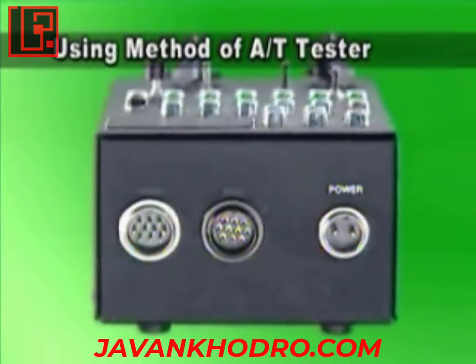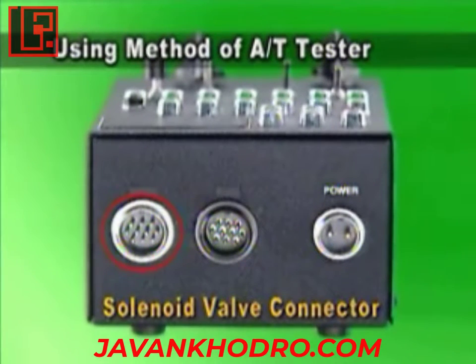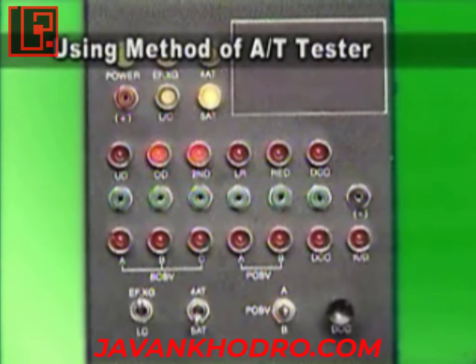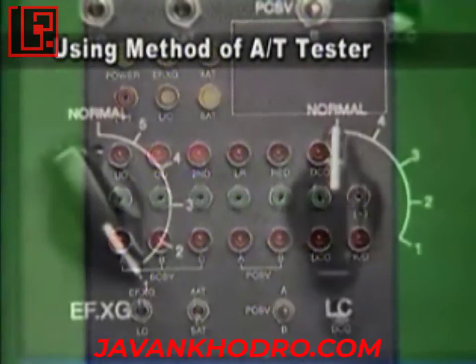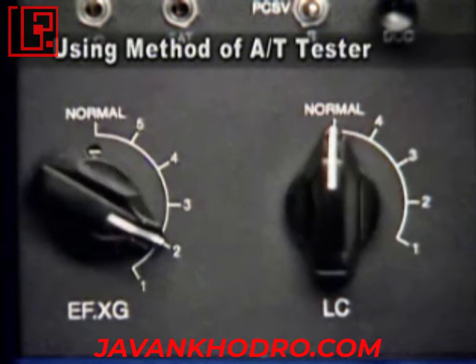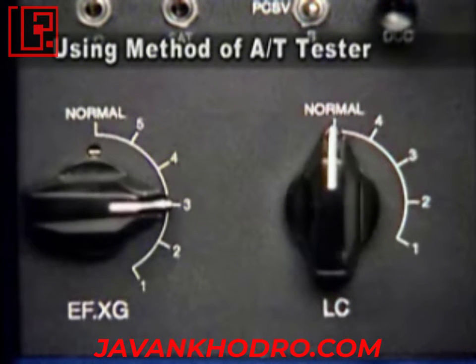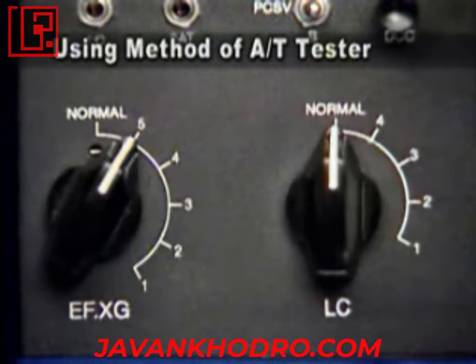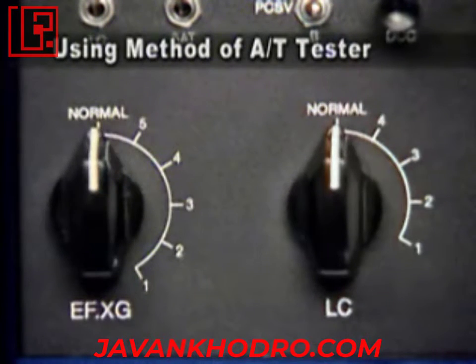Connect the auto tester power to the battery and disconnect the solenoid valve connector. And connect both harnesses together. Then, installation is completed. Select the vehicle model, 4 automatic transaxle or 5 automatic transaxle, and select the appropriate gear ratio. Then, any speed is feasible ranging from 1st to 4th or 5th speed.